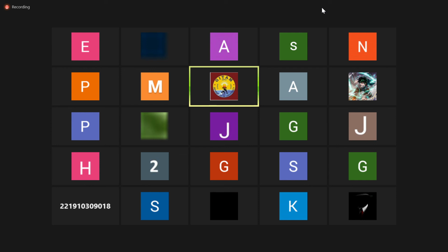And students, RTD we have analyzed in two parts. First part is static characteristics and second part is dynamic characteristics. Analyzing dynamic characteristics means we are using with sheath and with thermowell and how its response will be dragged. That is called dynamic characteristics. And static characteristics is whether that is producing a linear output or not. That is the first part. So we have taken 3 temperatures and we have calculated RT for 3 values and we have plotted a graph, and the graph we got as a linear response.